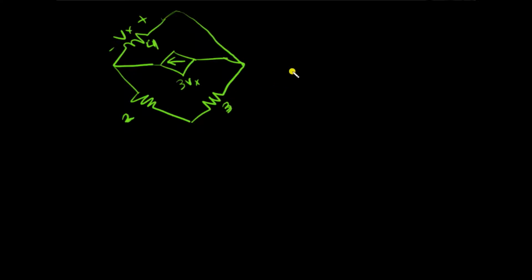Alright, so now I'll be solving one last practice problem for nodal analysis before we move on to our next topic, which is related to nodal analysis too. But this is a circuit and we need to find the nodal voltages of all nodes. So the first step is to mark out all the nodes.